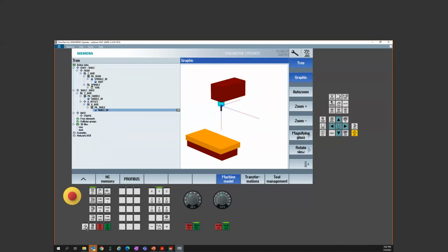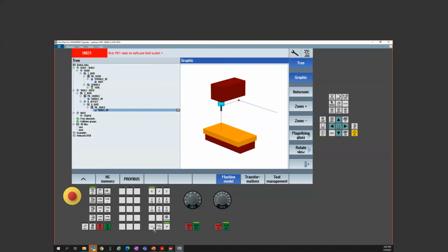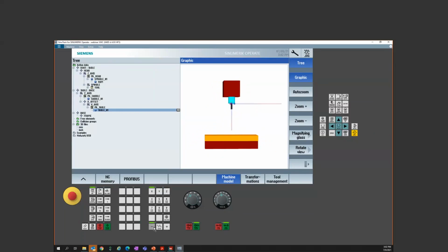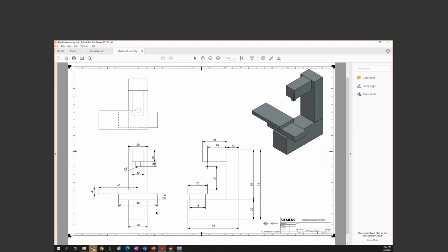And what's cool here is since that's dependent, right, I move my Y, my X moves with it. I move my X, it has no bearing on the Y. Now I have one other thing that's wrong. If you notice, I also need to shift and offset my X on the table because that's not right. I shouldn't be able to go beyond the table by half its travel. And that's because if you remember in the picture, when I'm at 0, my table shifted all the way to the left. So I also need a negative offset of its overall width of 40 inches.